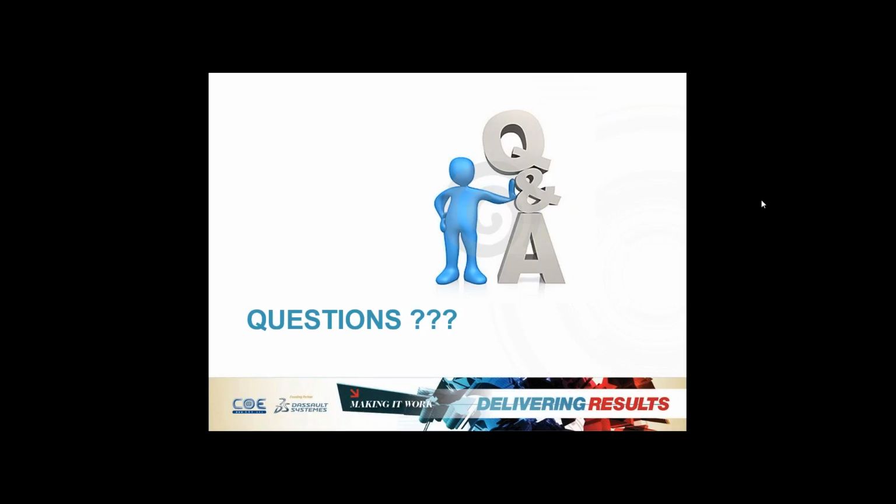Not that I know of. You can import an STL file in many different softwares, but it will basically be only an image, so you won't be able to pick points on it or use it to create profiles if you don't have this add-on package like we said about CATIA with the REE. So you could probably get a drawing from just an image to do basic views or snapshots, but not extract dimensions or lengths or distances or clean profiles. Well, not that I know of.